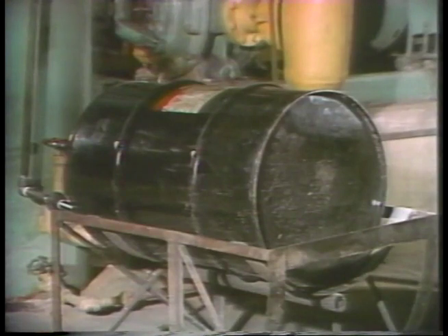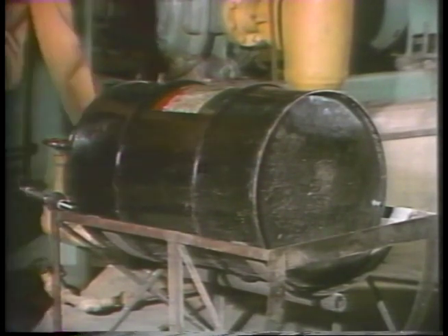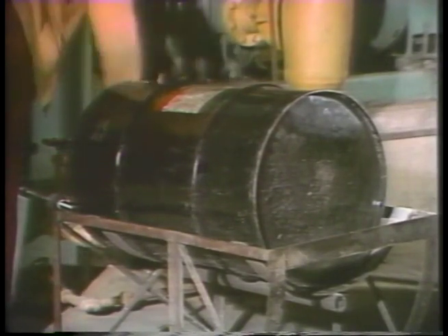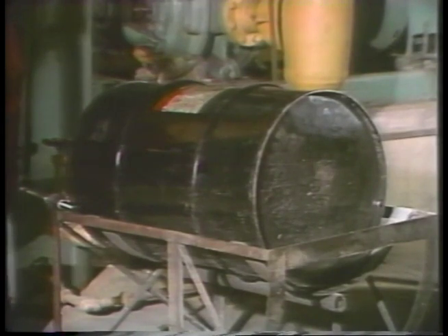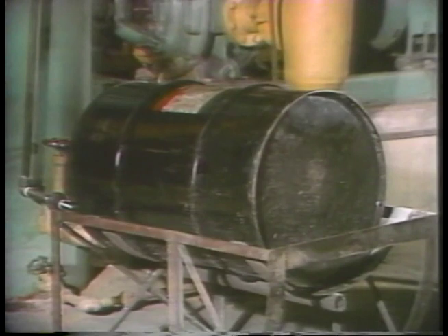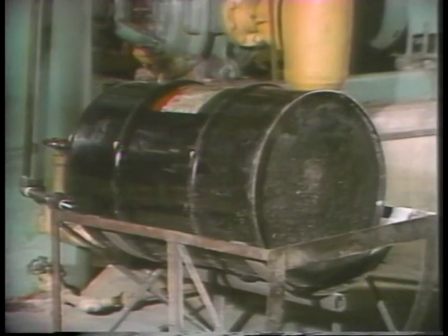Boyle's law also applies when draining a tank with the vent valve closed. We'll use this 55-gallon steel drum we saw at the beginning of this unit. The drum is filled with water and is attached to a receiver, which in turn is connected to a vacuum source. When we open the drain valve and remove the water, a vacuum is drawn, and the pressure inside the drum decreases. As the pressure decreases, the higher atmospheric pressure outside the drum pushes on it, causing it to collapse.